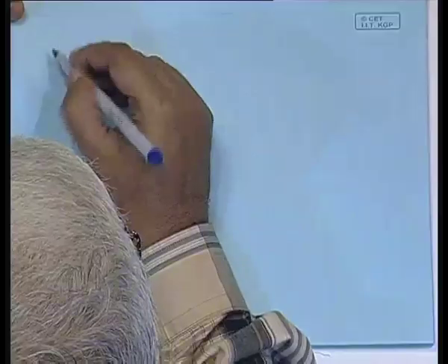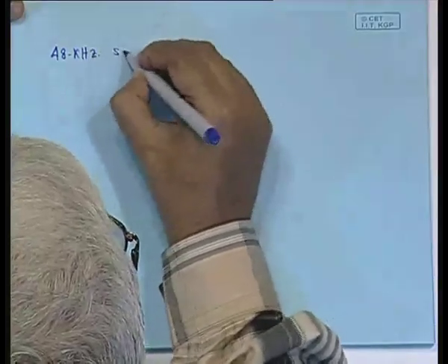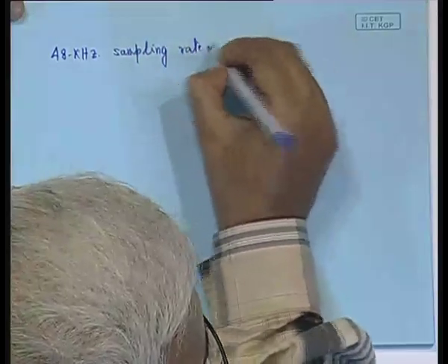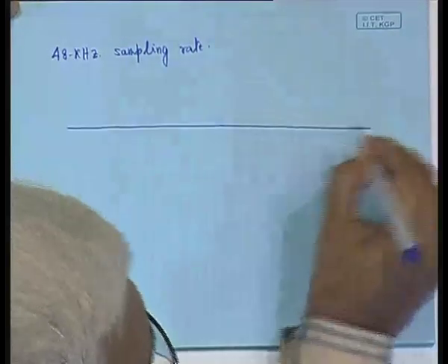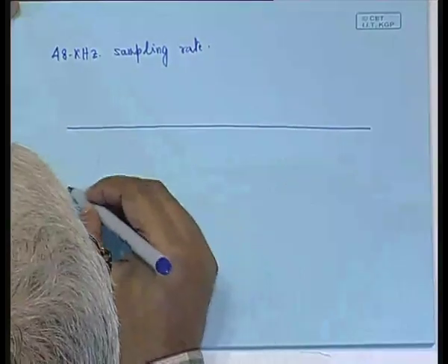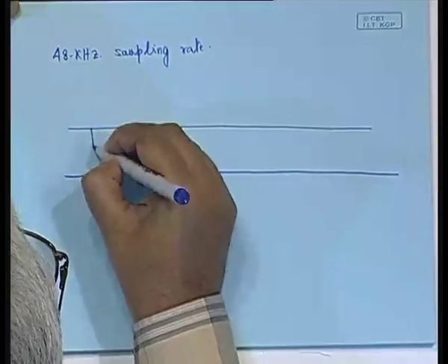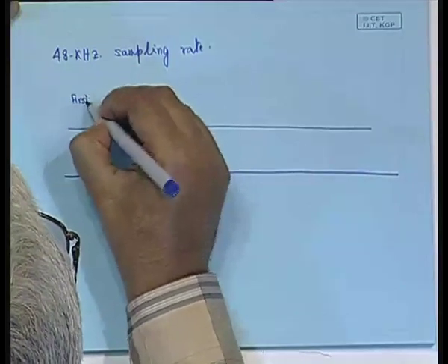So, the synchronization timing goes like this. This is assuming a 48 kilohertz sampling rate. With 48 kilohertz sampling rate, the timings are like this: the total time for a frame happens to be 32 milliseconds, and this is the instant where the first 2/3 of the AC3 frame is received.